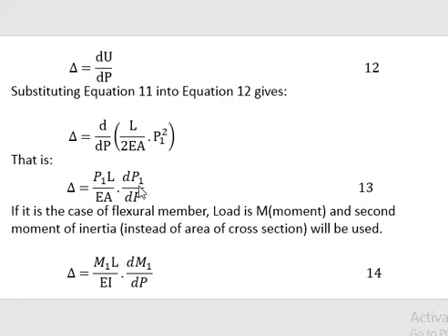If we do that, equation 13 will become exactly what is on equation 14. Whereas equation 13 can be used for truss members, equation 14 is used to analyze beams and flexural frames. In this case, we are dealing with moments, not direct forces.